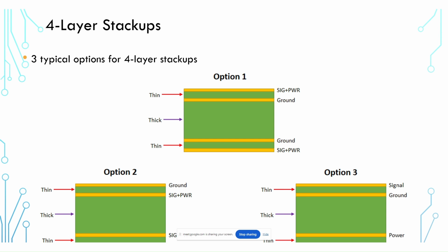So this slide shows some different stack-up options for the cases where you do get to a very dense 2-layer board and need to add 2 more layers in order to provide ground. There are some variations of this that I've seen people discuss with me recently and have asked questions about for videos, and so I decided to show them here.